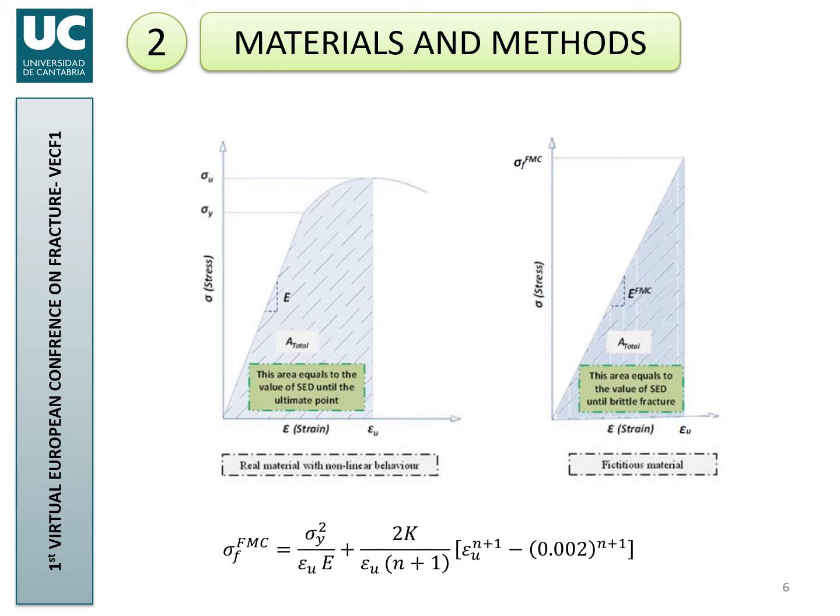So on the right side, we just have to change the slope till the area equates the area on the left side curve. By doing so, we obtain the tensile parameters in terms of Young modulus and ultimate tensile strength of the fictitious material. This latter value is straightforward, as it is given by the formulation shown below.